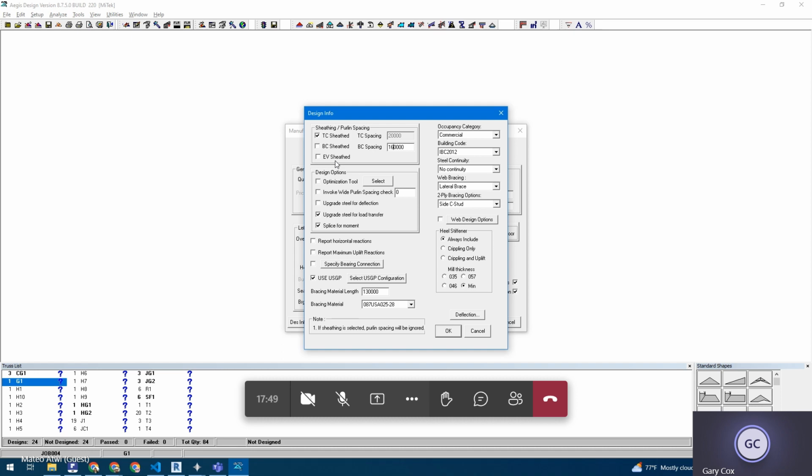Got it. And if you type anything with a decimal in it, that's decimal feet, is how this program works. Oh, that's kind of handy. So this is decimal feet, but AutoCAD's decimal inches, so you have to remember that. And you can't use the tick marks in here either. It'll probably crash on you. But you can make it show that way. There are some dimensioning options to make it look that way, but you can't enter it that way.